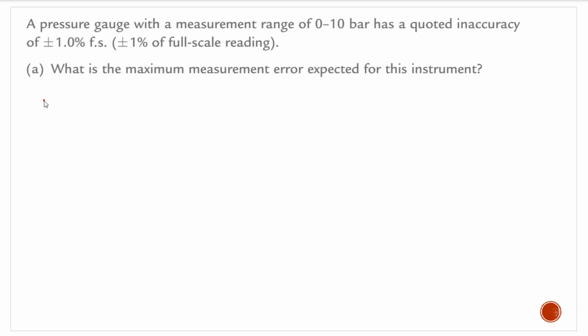Now, systematic errors के causes, they can be environmental causes, they can be the inaccuracy with the instrument itself, faulty nature of the instrument, faulty design of the instrument. All those things will lead to systematic errors. Random errors will be because of, say, for example, human interaction with the device. The observer may not be properly measuring, or because of the reduced capability of the observer, there may be errors, and these types of errors can be both positive as well as negative for the same set of readings.